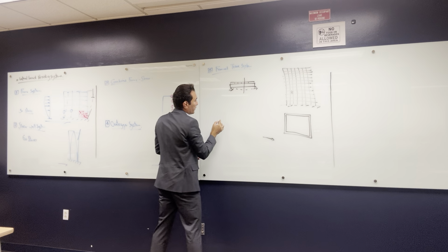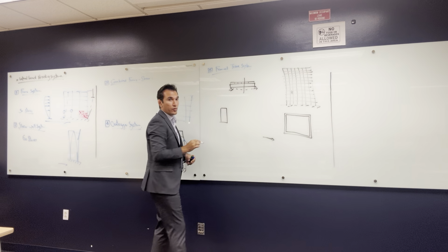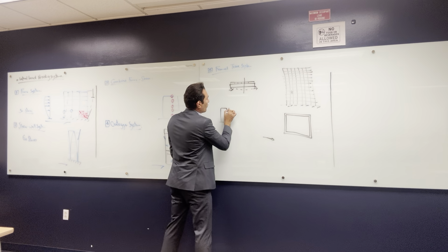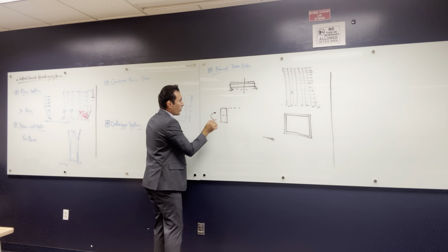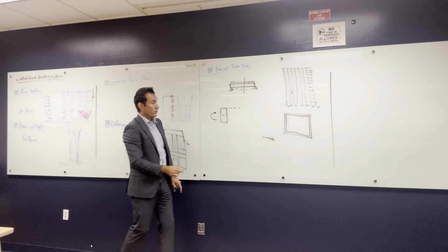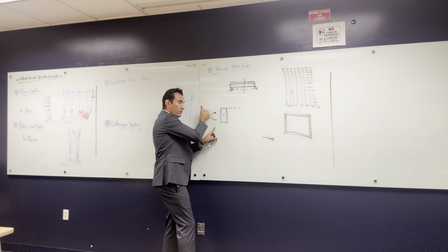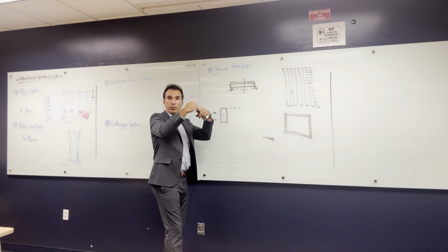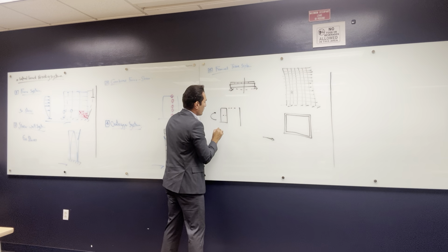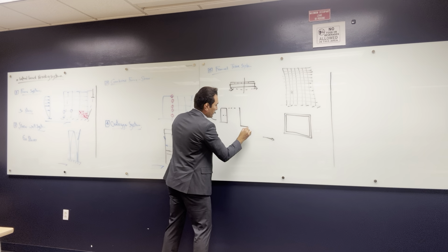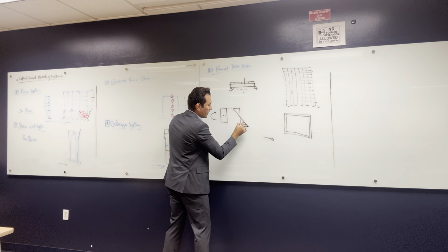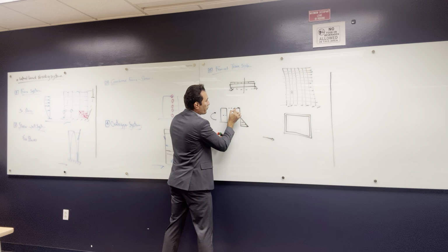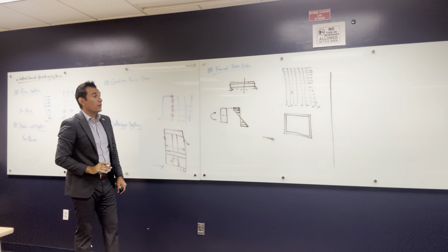And if I take a cross section here, and I wanna look at what's going on stress strain wise on this cross section. So, this cross section has a bending moment like this. Where's the tension and where's the compression? Tension is down because that's the moment, and it's making compression on the top, right? So the stresses are gonna be something like this. This one is making tension, so that's the weight. It pulls the cross section, and this one is compressing the cross section, right? That's how it looks.